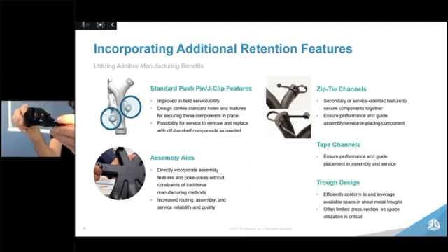Within this part, there are standard fitment accommodation, so a hole here and some other bosses and holes here within the part, and those can accommodate things such as push pins or rivets or spring clips, or fir tree fasteners can be housed, for example, and that gives you the ability also to create standoffs and fitting guides.